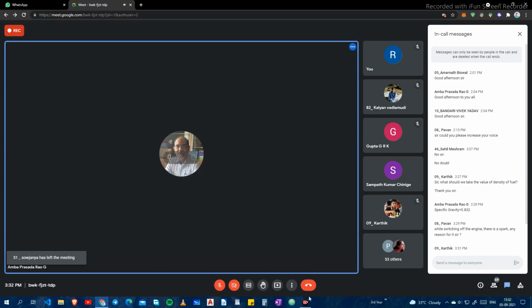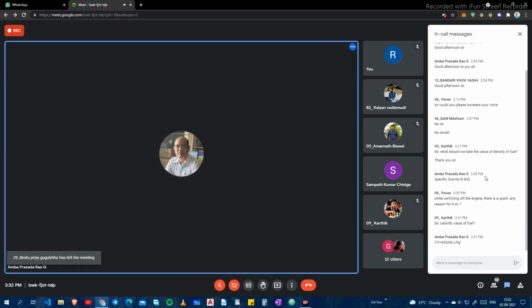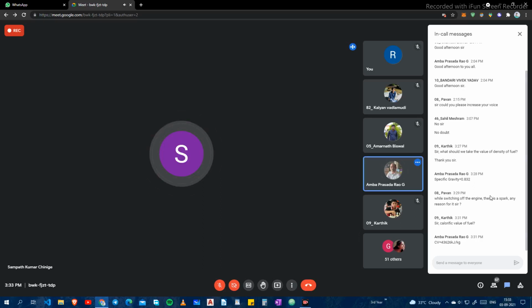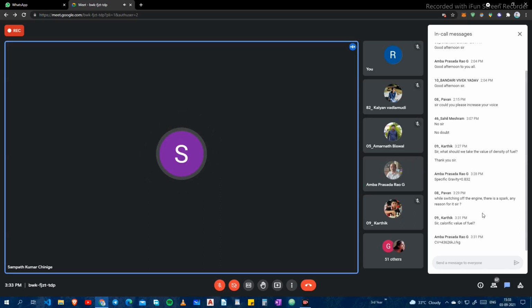Yes, sir. Last class you asked some questions. Do you have anything, or did you clearly understand what we explained? Okay, Dr. Sampath. So calorific value, how much, sir? 43,626 is what is mentioned in the manual supplied to them. Correct. So in kilojoules, 43,626 kilojoules per kg.